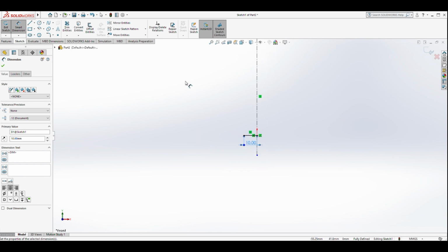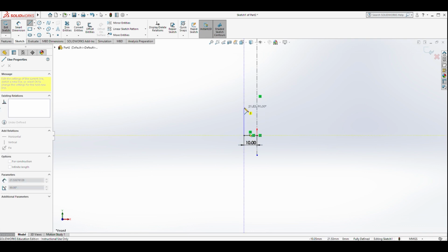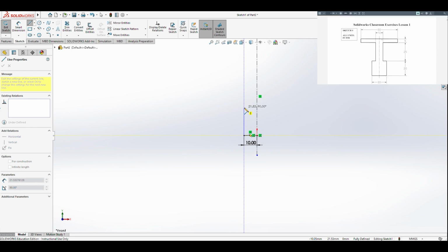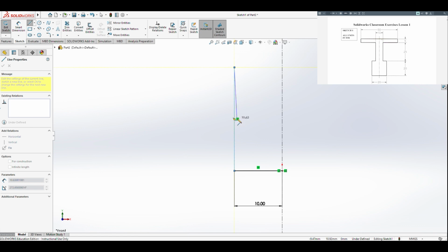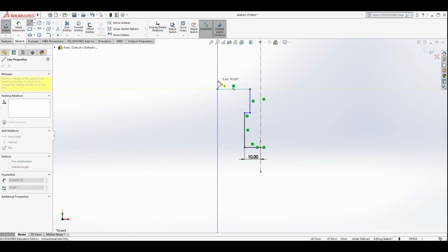After you guys get that set up, you're basically just sketching in the shape. So you're going to make a line that goes straight up and down here. And I'm going to be very aware of these little green icons. This means horizontal, and this means completely vertical or plumb. And we're going to make another horizontal line that comes up like this and sort of comes out like this. And we're just creating this outline.